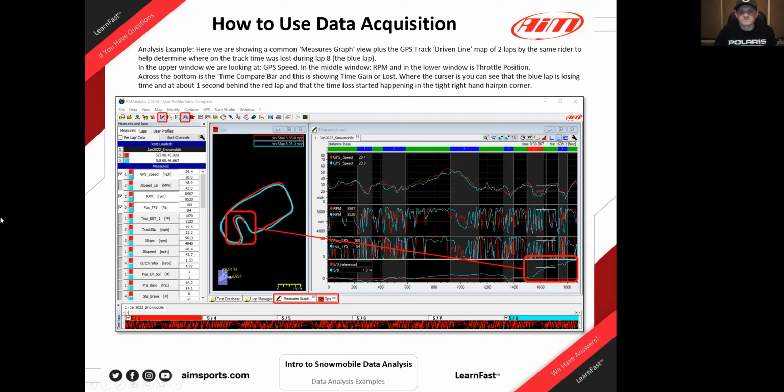So, okay, the main thing about looking at this one is understanding that we can add the GPS in for position on the track. You don't have to remember it by these squiggly lines and a little bit harder to understand where you are here, but we've got some mapping functions. And then the biggest thing I wanted to add into this one is this whole thing about comparing laps, either from a teammate or even you against yourself. In this case, 2 of your own laps, and understanding where you were slower and how much slower based on the time compare bar. Very, very important piece.